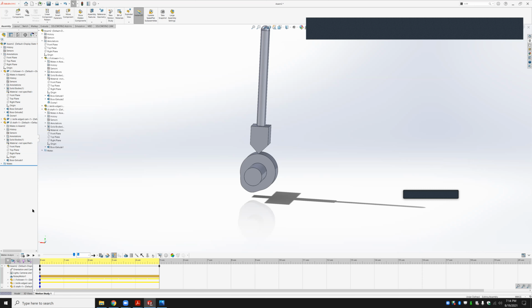What you could do, which is what I did, is you can go back, start the mate command, and drop down your shaft part over here. Oh, sorry, follower. Yeah. So drop it down with a little black triangle. And then hover over your plane. So probably the front plane looks good. So you can select that and then drop down your shaft over here. Black triangle is fine, left of the shaft. And hover over these planes and see if good. That looks good. So yeah, you do the right thing there.